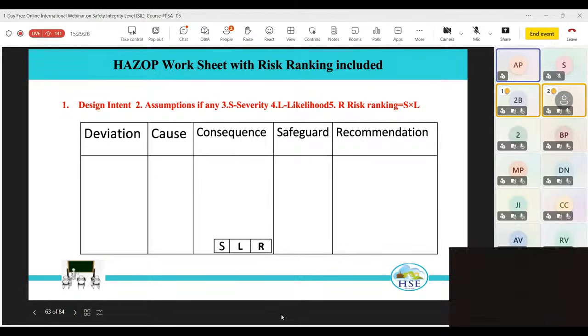Suppose you have a BPCS failing very regularly. Now there is also confusion for people. They consider BPCS failed in only valve fail or only transmitter fail, which is not correct. Once we say that this failure has happened, we consider the entire loop failed.